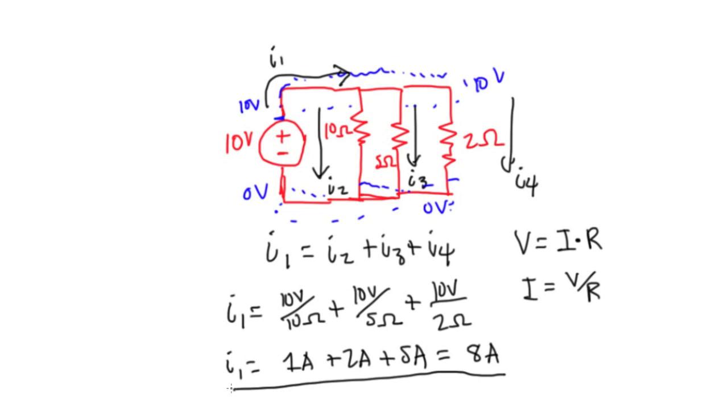And that's just a basic example of how you can apply the Kirchhoff current law. In fact, you can test this yourself. What you can do is change the arrows, flip them around, and you'll find out that you get all the currents as negative values. You can try that yourself. And the trick to keep in mind is that when you go from 0 volts to 10 volts, the voltage difference is not 10 volts, it's negative 10 volts. That's something to keep in mind when you do that calculation.